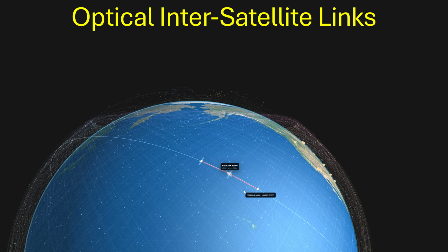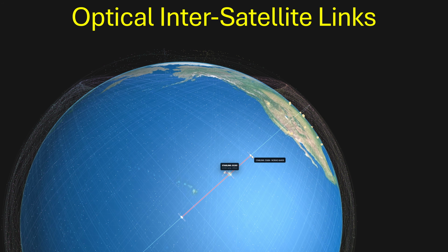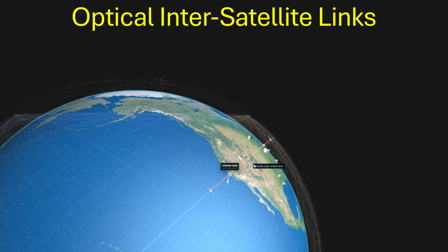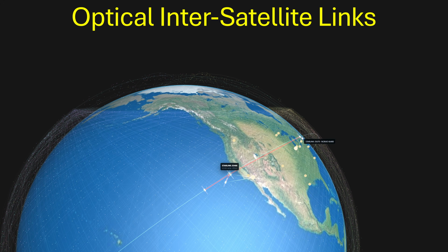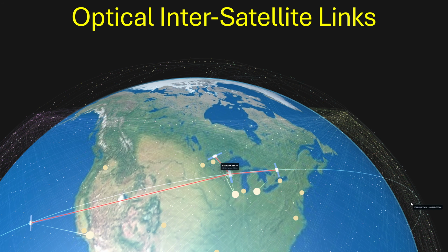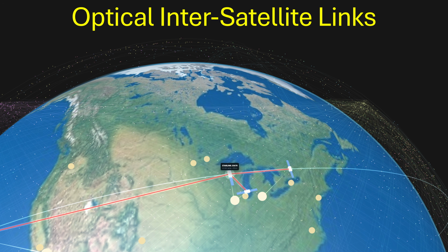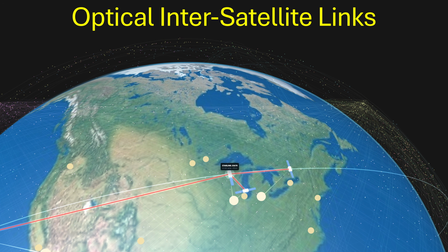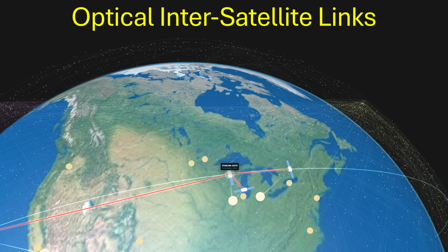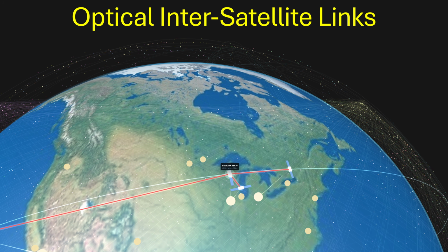This is why Starlink V2 Mini uses 3 200 gigabit laser terminals per satellite, one of which is cross-plane. These cross-plane links can be much shorter, often less than 200 kilometers. However, there is much more relative motion between these satellites, and they need to switch when the connected satellite moves out of view. So these links likely require a more advanced pointing system and a dynamic routing system to optimize all of these connections across the constellation.